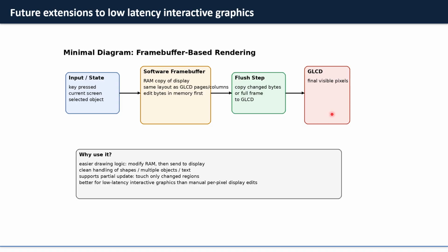We should try to reduce our interactions with the GLCD per frame as much as possible, because these are sent through wire lines and control lines, and interacting with the GLCD RAM is a slower, higher latency task than directly interacting with the CPU RAM.